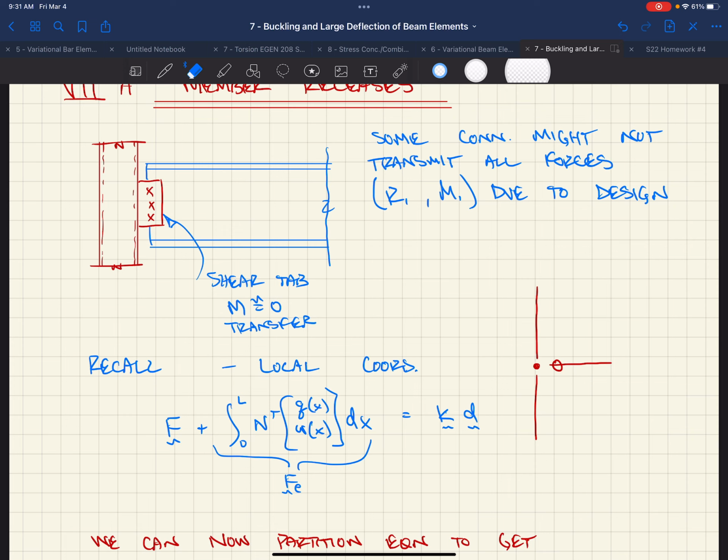We kept stepping back and being like, this doesn't make any sense. Like looking at reactional forces and validating, saying, okay, I have my forces that are hitting this building, right? And we distribute those vertically, and so we kind of have story forces understood. And the roof's usually a flexible diaphragm, so you kind of chase those loads. And so in a general sense, you have a feeling for the magnitude.